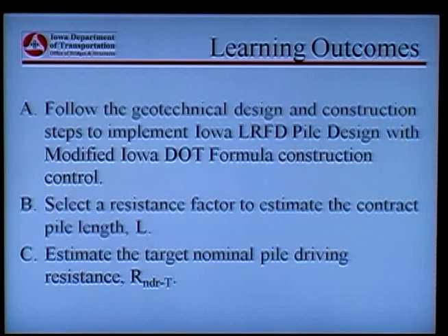Select the right resistance factors from the table that I showed you previously, for design as well as for construction control, and come up with the contract length that is required, as well as the target driving resistance required during construction. Right?